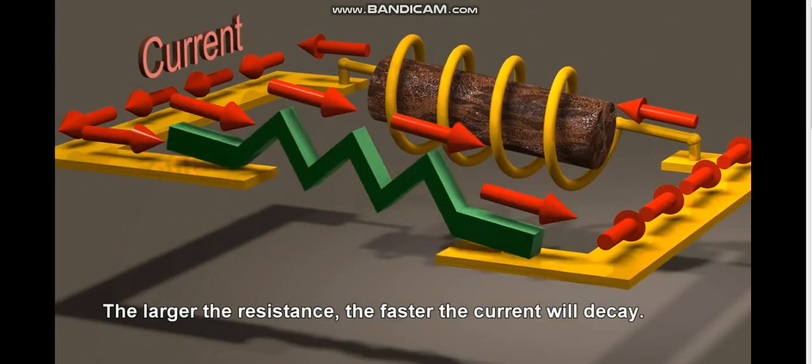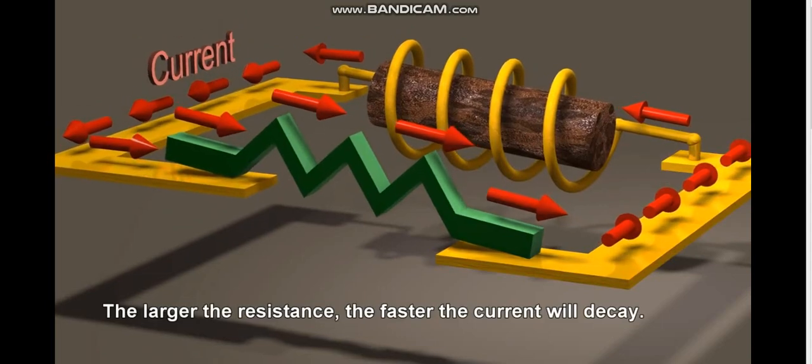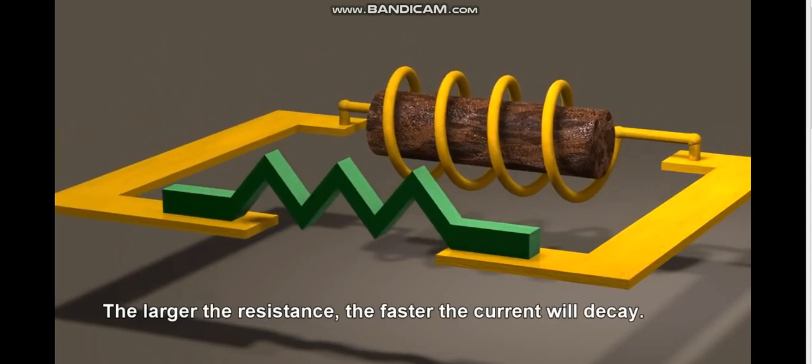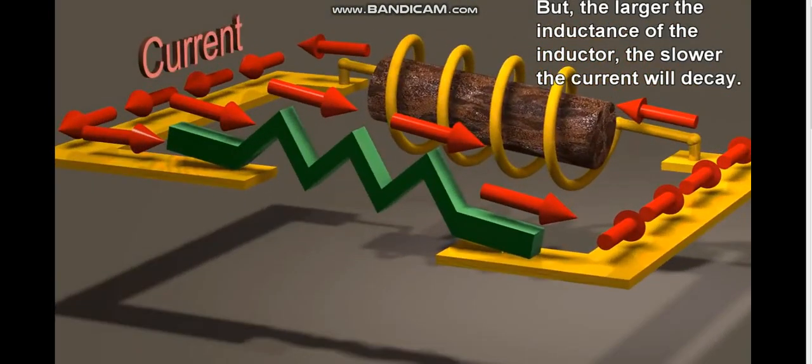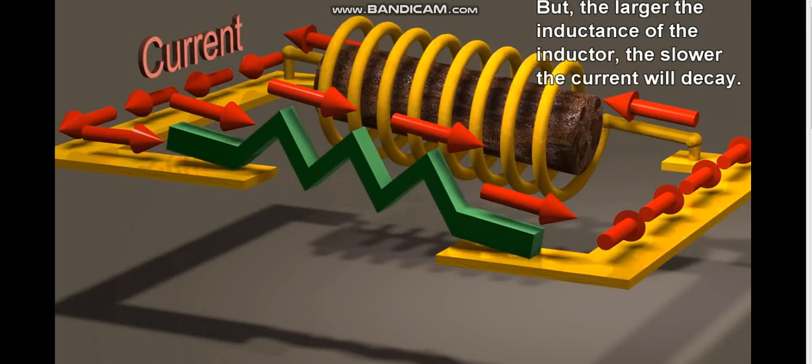The larger the resistance, the faster the current will decay. But the larger the inductance of the inductor, the slower the current will decay.